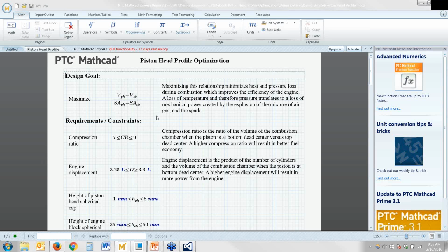that heat will escape from the combustion chamber in the engine through surfaces. And so once it gets in contact with a metal surface, you have conduction and heat escapes. The more heat that escapes, the less efficient your car engine is. So you want to minimize the surface area that allows heat to escape as well. And so this is actually a fairly common calculation in the automotive industry that engineers try to maximize in order to get that shape just right in the combustion chamber.